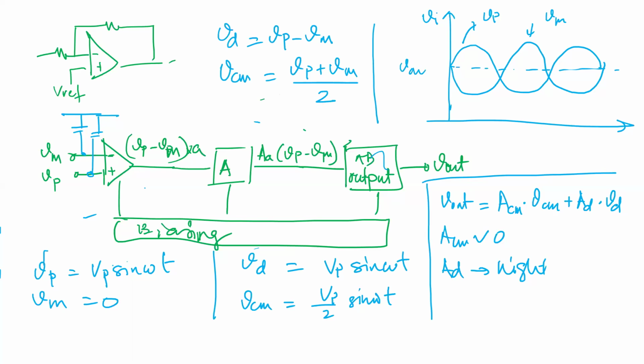And we'll try to build that with a simple differential amplifier stage. You got it? So what we'll do is take what's called the differential stage. I think people who have done analog are probably aware of it. And then we'll put a load on top, which is your current mirror load, and that should give you the output over there. Okay, got it?